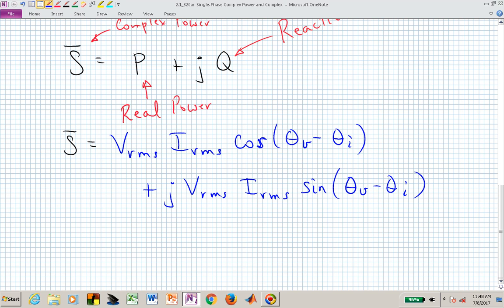And we also have an angle that's the difference between the voltage waveform and the current waveform's angle. We have theta sub V minus theta sub I, and that's like the angle of an impedance. So you could say that this is an impedance angle for a given element, or I should say system, and that system could be an interconnected network, and so you might have theta sub V minus theta sub I being positive or negative, but some value between 0, let's say, and plus and minus 90.